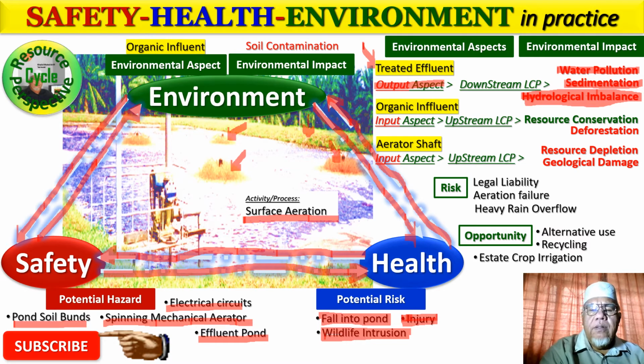High nutrient levels in this water, remember there's still BOD, would cause perhaps some form of eutrophication, excess nutrients in that river, and you've got worms, you've got all sorts of additional load of microorganisms into the river that would of course be a luxury to some species of organism, and there is an excess of certain organisms, and that would also disrupt the food chain of the receiving water body, of course at lower trophic levels, not at high trophic levels, and it's not quite evident to the human eye.